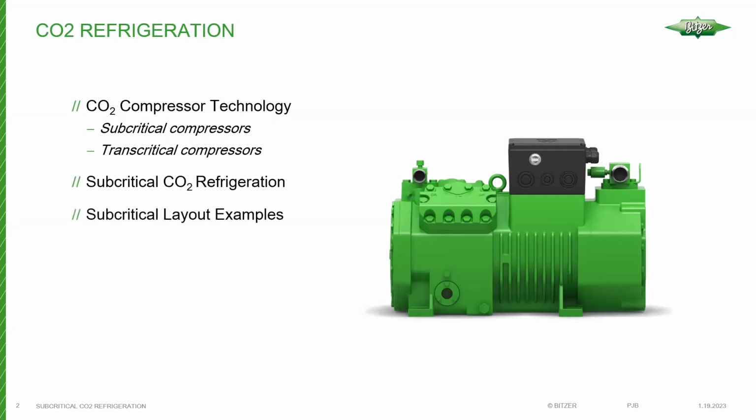So initially, we're going to take a look at some CO2 compressor technology, again, subcritical and transcritical compressors. What makes these compressors different than HFC compressors? Subcritical CO2 refrigeration, what is it? What does it mean? And also we'll take a look at some subcritical layout examples.